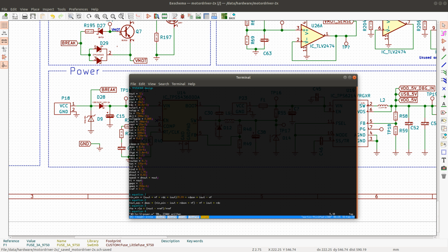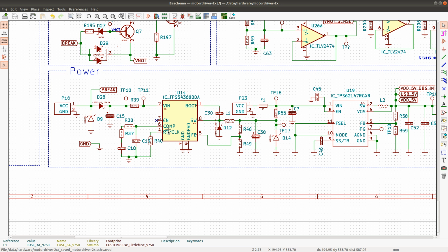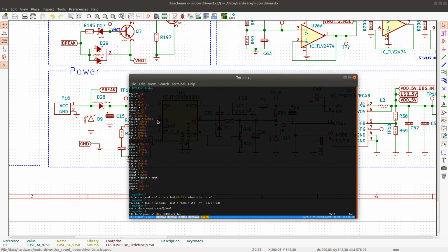And then there is another voltage that specifies when the regulator will power off. This calculates the resistor divider that goes to the EN pin, but the pin can be left floating because it has a pull-up resistor inside the chip, which will power on the regulator whenever the voltage reaches, I think, the minimum input voltage calculated using the equation. But for the sake of the calculation, I specify the minimum startup voltage of 17 volts and the minimum voltage before it powers off at 14 volts.